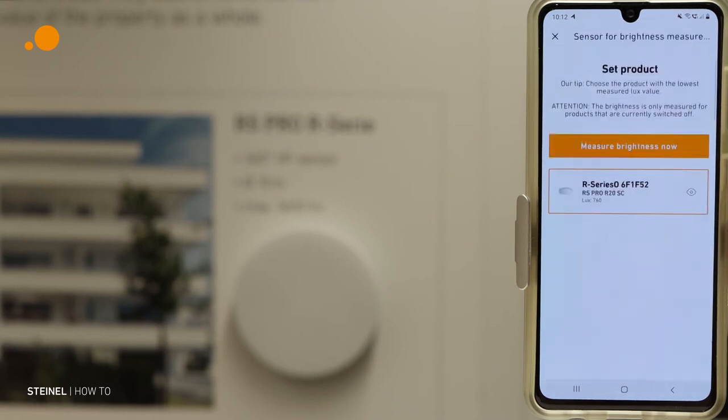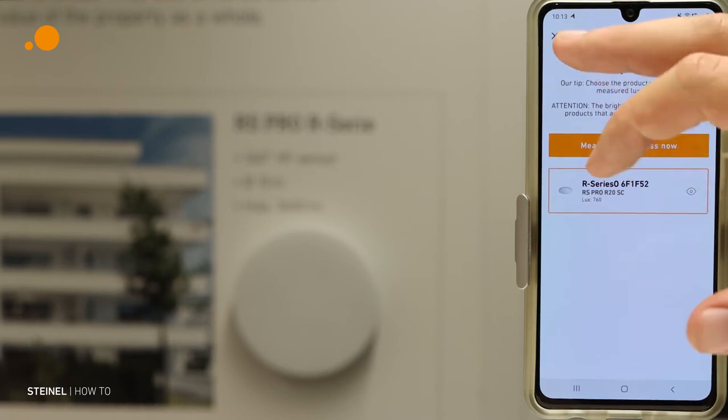Here, when we have a list of luminaires, we can say which luminaire should give the light level threshold to the group. We see here the lux level of each luminaire, and then we can set, for example, the darkest luminaire to be my master for the light measurement.